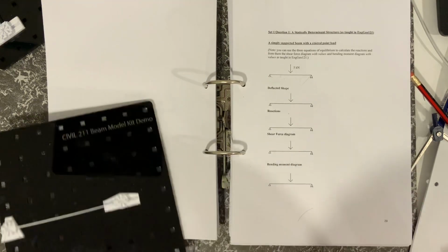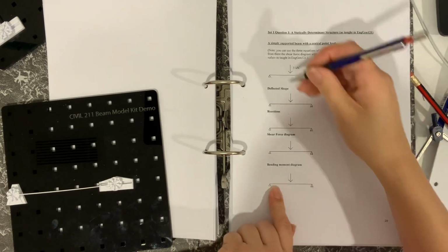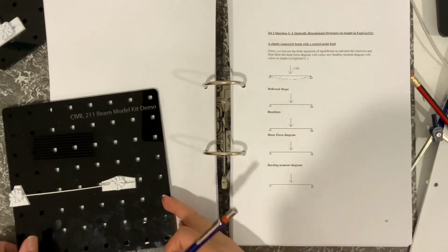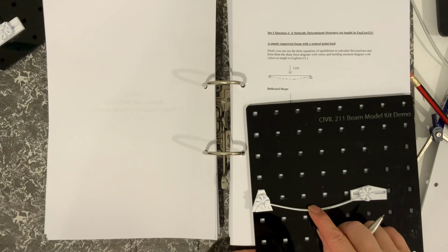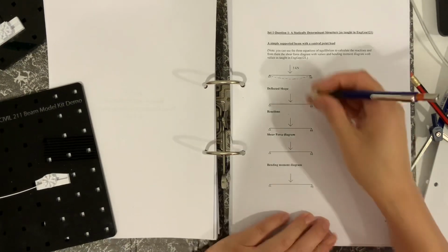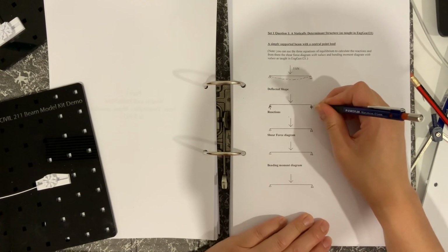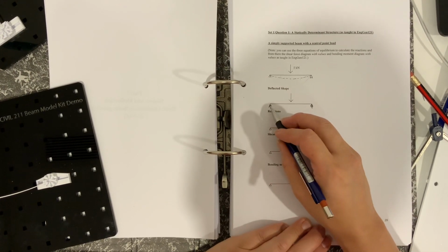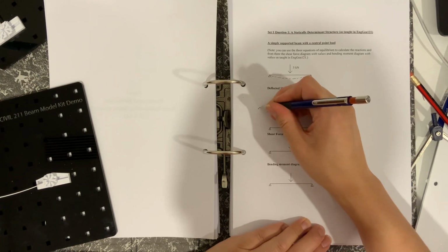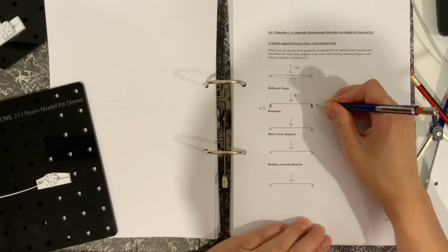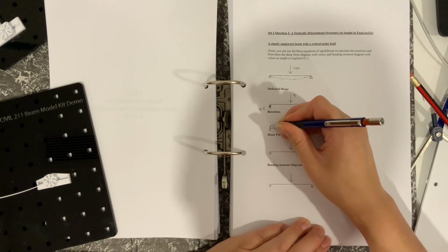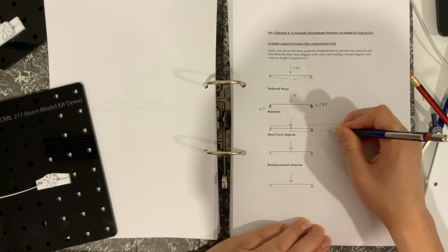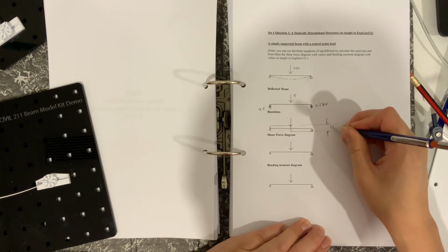That becomes the tension side. So we can draw the deflected shape like that, which would be the same as here. The reaction is half here and half here. The shear force diagram follows the direction of the actions, which would be that and that and that. So that would be 2.5, 5 and 2.5 kilonewtons. So the shear force diagram would go down there, go back up, and then that distance there, of course, would be the 5 kilonewtons.